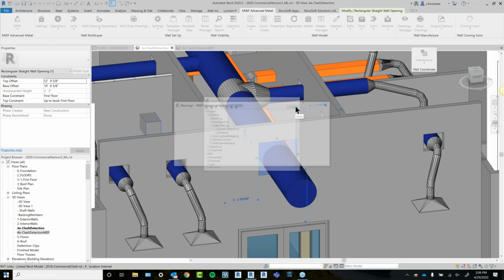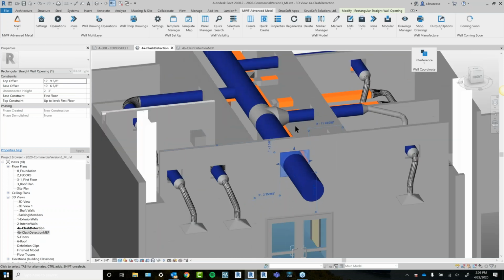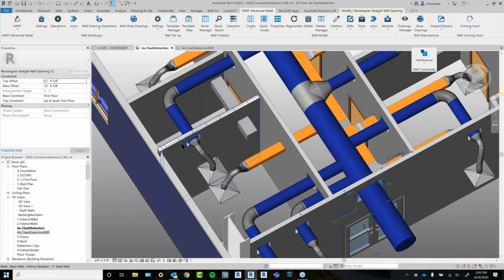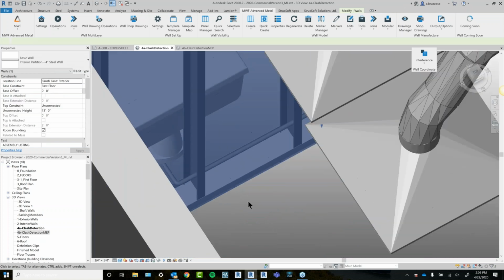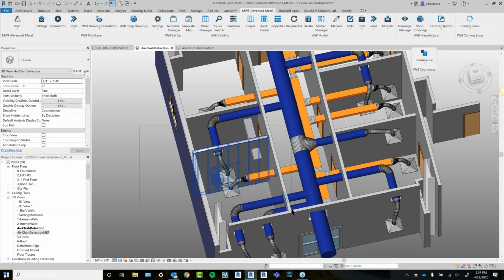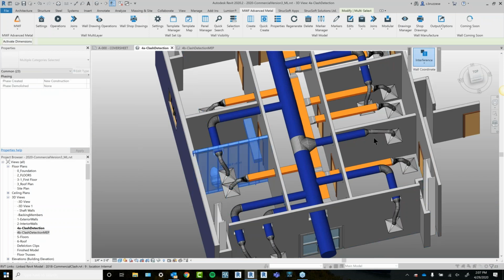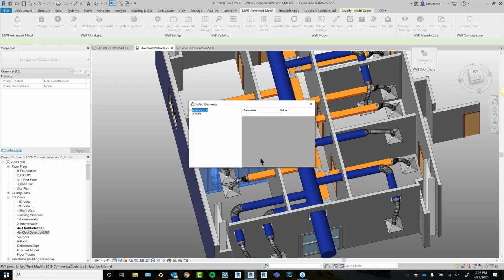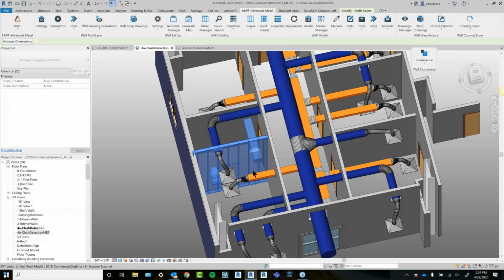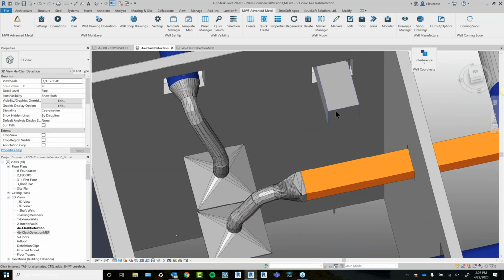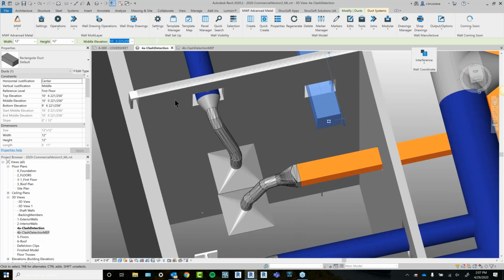So that's the clash detection that's been used on this guy. And I'm also just going to point out one little thing. Let me go rerun Clash on this particular wall. So on this particular wall, two things I just want to highlight. I've got an actual element which isn't linked in, which I'll talk about in a second.